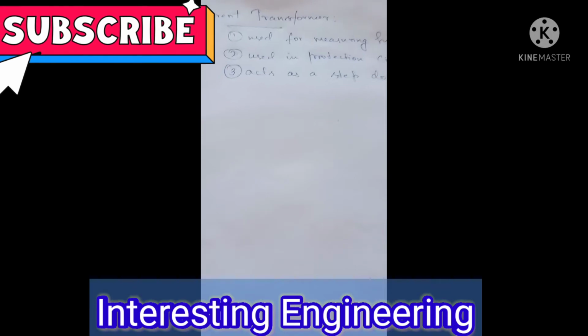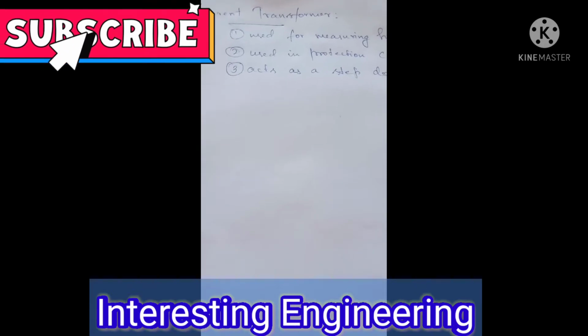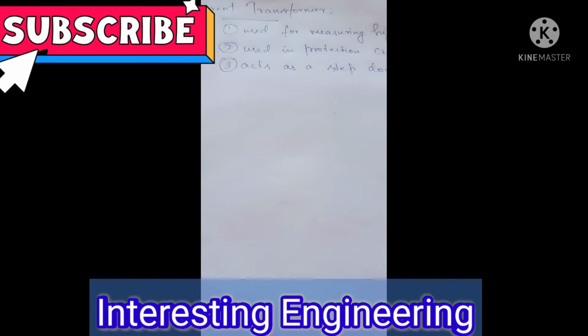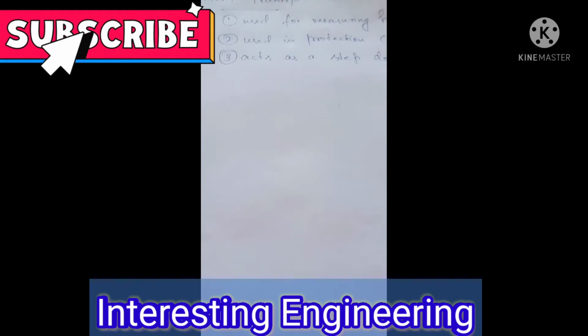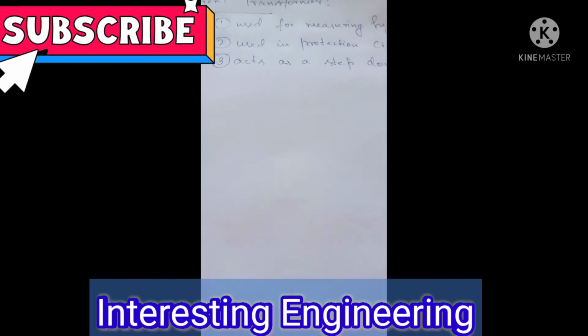That is, similar to a power transformer, it too has a primary and secondary winding, and based on the current flowing through the primary winding, flux is created. That flux links with the secondary winding and an EMF will be developed. Based on that principle, this current transformer also operates.